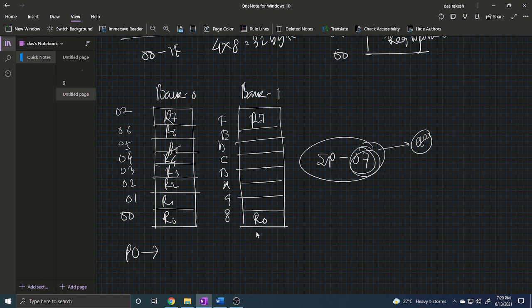Why? Because from the concept of circuit theory or digital electronics, we know that for a TTL gate circuit, this is basically an open drain connection, because the 8051 is basically NMOS technology. If a transistor is used, then we call it open collector. But as this is developed by MOSFET technology, it is called open drain. So open drain is a term used for the MOS chip, in the same way that open collector is used in TTL chips.